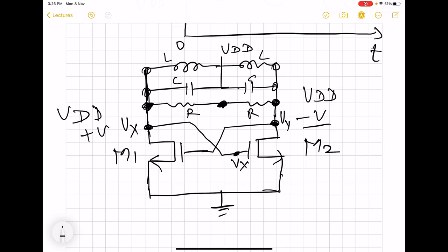Now, these capacitors are not going to allow any DC current through them, and otherwise also their other ends are at the same potential. So here also there is no need to connect VDD at the common point of the capacitors. And for AC, their behavior is not going to be affected, because this will be ground, with plus V here and minus V here. Only for this inductor, we just need to connect it to VDD. So that scenario remains similar to what we had earlier.